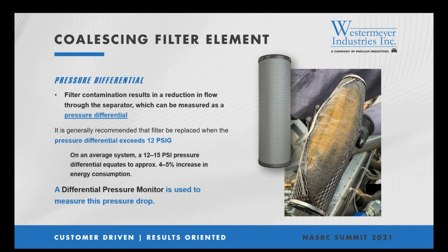So this is a balance. You need to ensure that you are monitoring the pressure drop to keep your energy costs down and to prevent a catastrophic failure. But if you don't know when to service your oil separator, you may be changing the filter too often, which will increase your service costs. A differential monitor should be used to measure pressure drop across the oil separator.